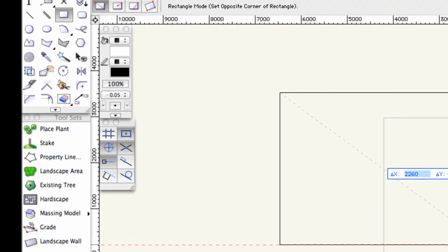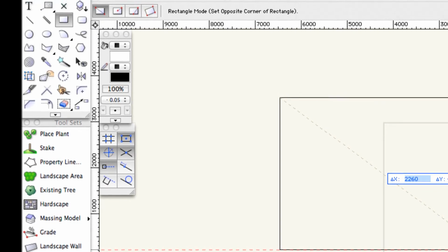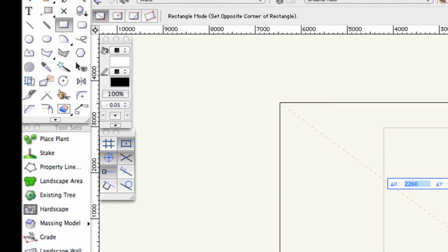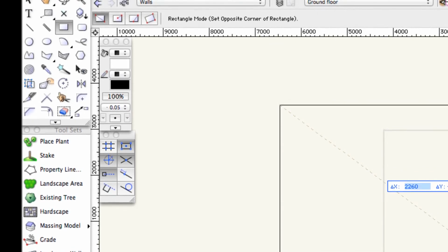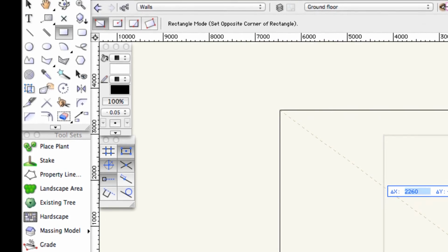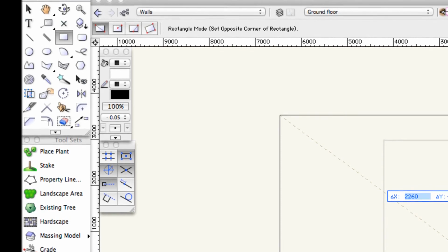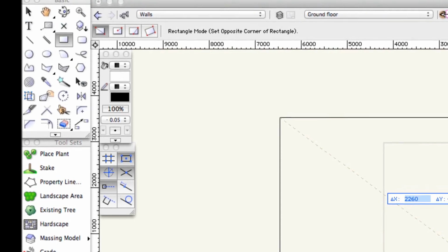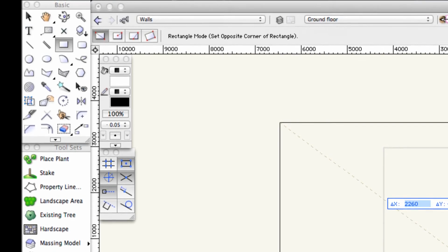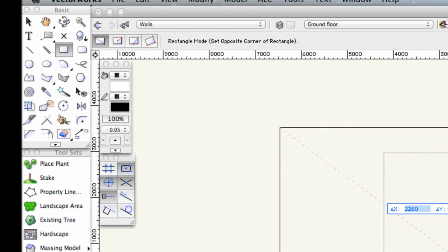During the session we had some nifty little tips on how we can do different things in different ways. For example, instead of trying to get our rectangle exactly in the center and changing the shape size by using the object info panel, we instead dragged the rectangle tool and did not click, but used the tab tool to change the variables, as shown in the image here, from 2260 to 4000. This was a lot easier and quicker than going all the way to the object info and then changing it and going back.